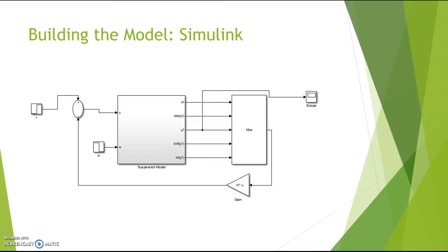The next step is to implement the full state feedback control. Before we can do this, we need to make some changes to our model. We need to generate several state outputs. These include the difference of the velocities, the position of x1, the velocity of v1, the input step w, and the controller force. This system is now copied into a subsystem which outputs the 5 scalar state variables previously mentioned.